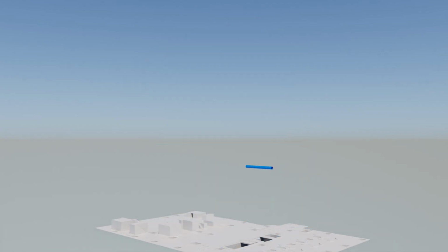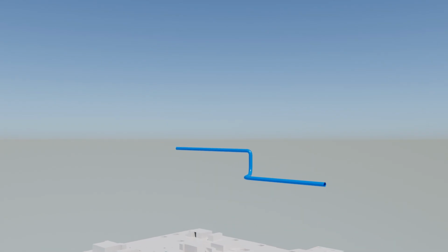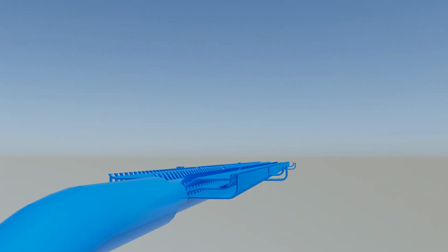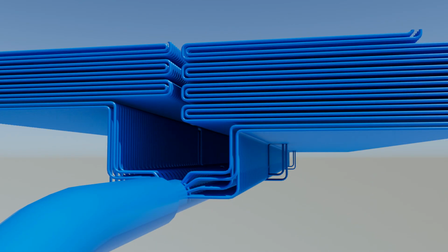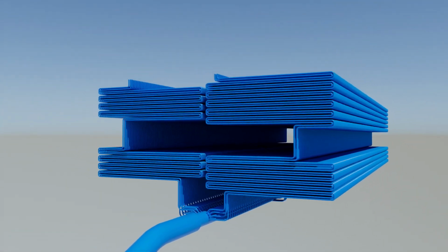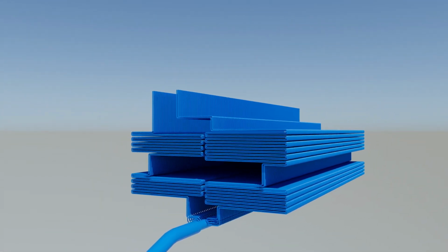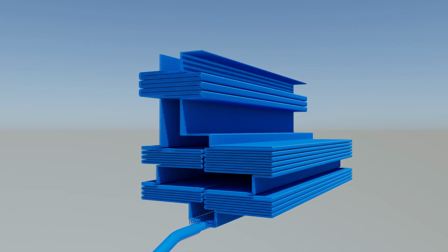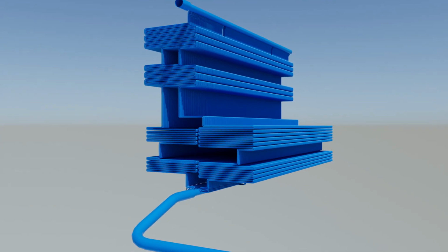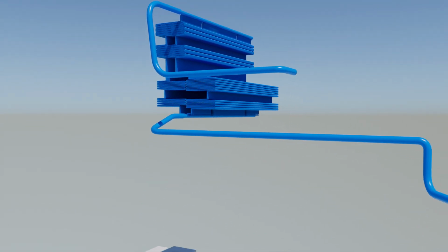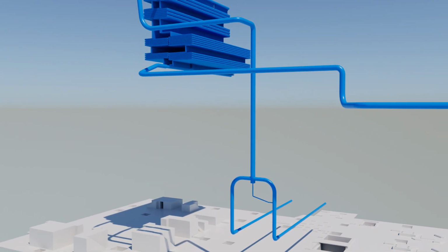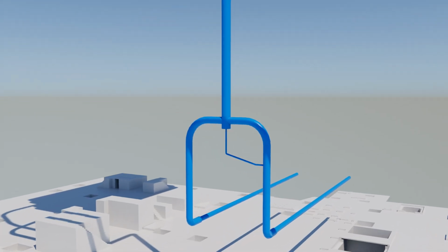The feed water from the outlet of the HP heater enters the Economizer inlet header and flows to the Economizer outlet header. The Economizer consists of the primary and secondary economizers, which are located in the HRA. Primary economizer consists of bare tubes. Secondary economizer consists of bare tubes. The flue gas flows across the economizer tubes in a direction opposite to the water flow.